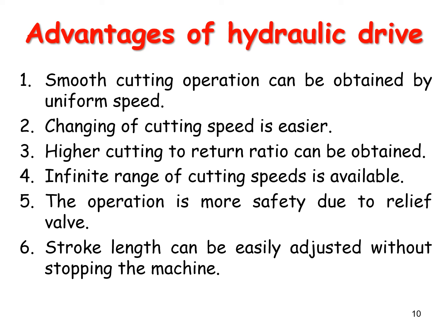The operation is safer due to the relief valve. In case we are not able to control the forward and backward stroke, the oil pressure will automatically be released with the help of the relief valve. The stroke length can be easily adjusted without stopping the machine. So these are some of the advantages of the hydraulic drive.